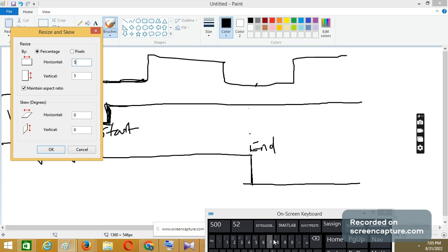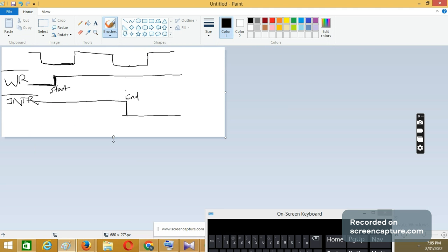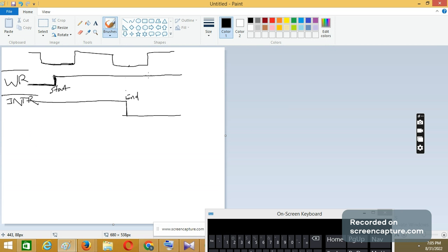Now, after conversion has ended, the microcontroller can read by giving a read signal. How to give the read signal? Initially, it should be high. After the end of conversion, it goes low to say that I want to read. Okay.